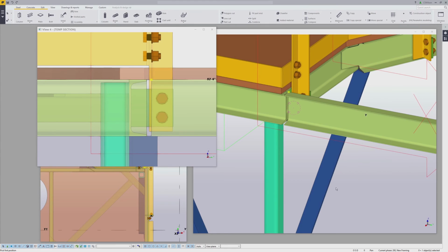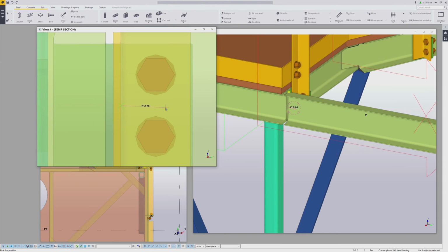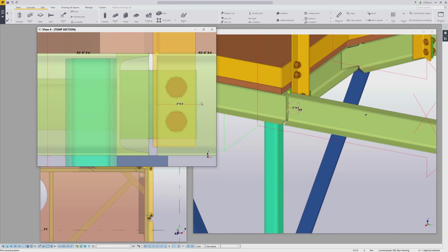Apply and OK. So I'm going to give a control point at the midpoint of the end of my beam. So a control point. Then we're going to go over with our ortho on 2½ inches. We're going to give the starting point there.